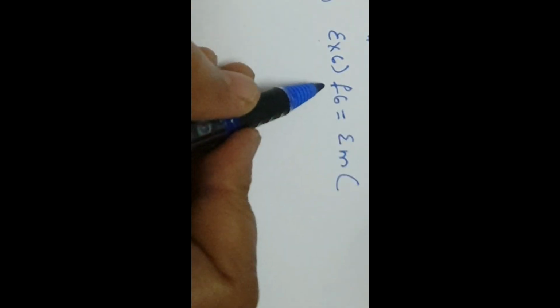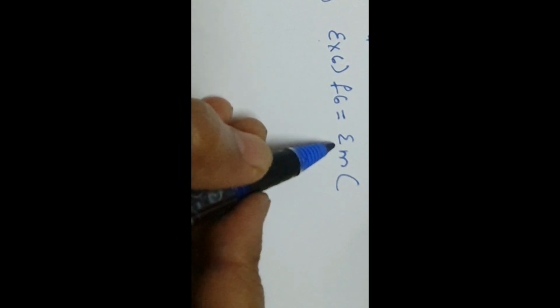So next, one more example we shall consider. That is the last example, example 6. Here simplify F6 = sigma m of 1, 3, 4, 5, 6. So the biggest number is 6 here, minterm 6. 110 it is in binary. To express this, 3 bits are required. Hence this given expression is also a 3 variable expression.